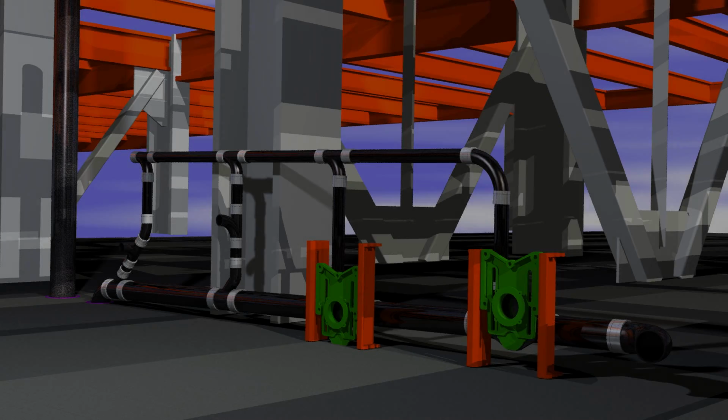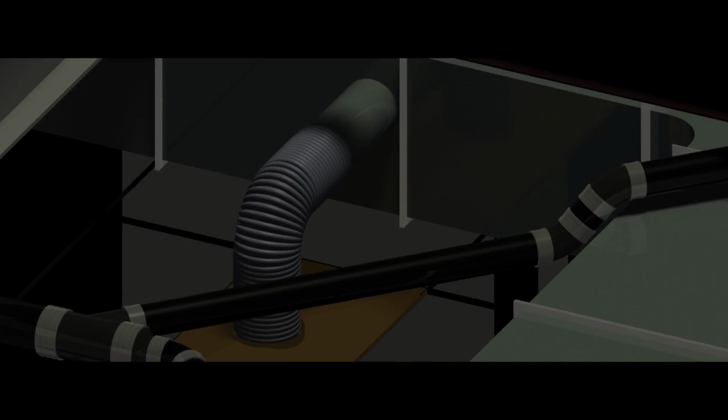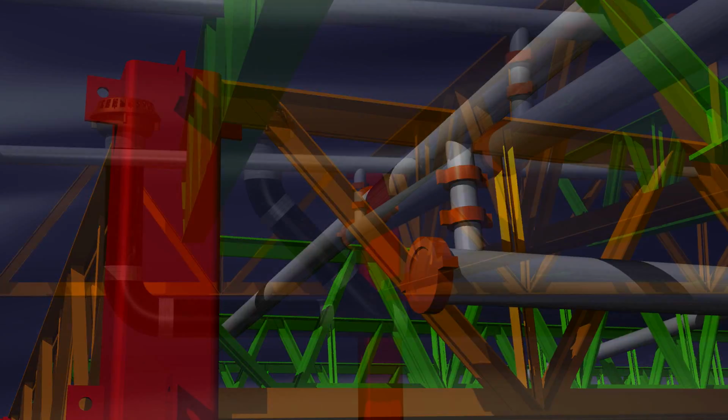Additional instructional videos will show the versatility of the slide routine when used on sloped or graded pipe runs. Real-world examples in these videos will include lav and toilet headers, associated rolling offsets, and the use of the slide routine to avoid collisions with other 3D entities such as structural members and ducting.